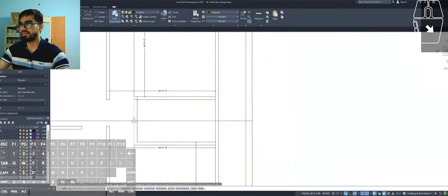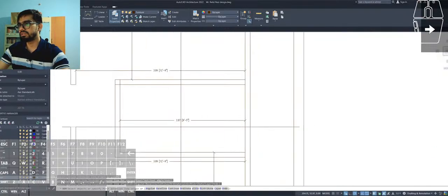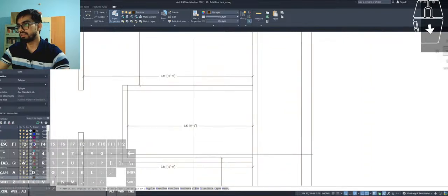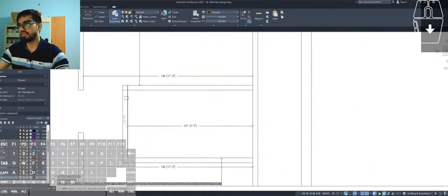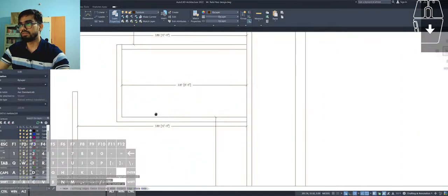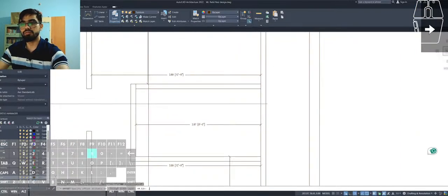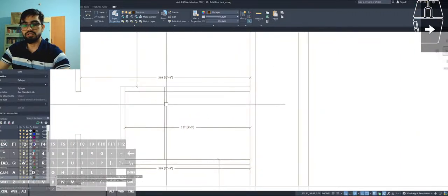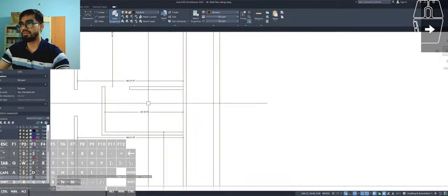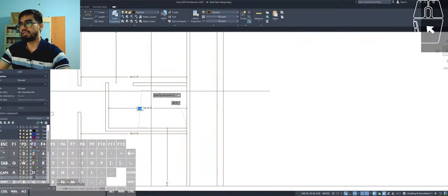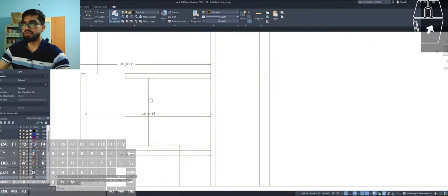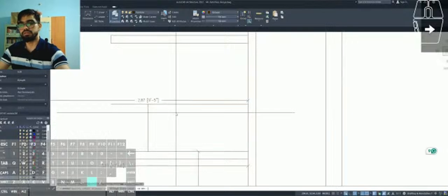What is this space? How much is it? 9 feet, 3 meters. And remove this and then have 0.9 like these, and then trim, get in the middle, go here, offset 0.9, trim, offset 0.115.